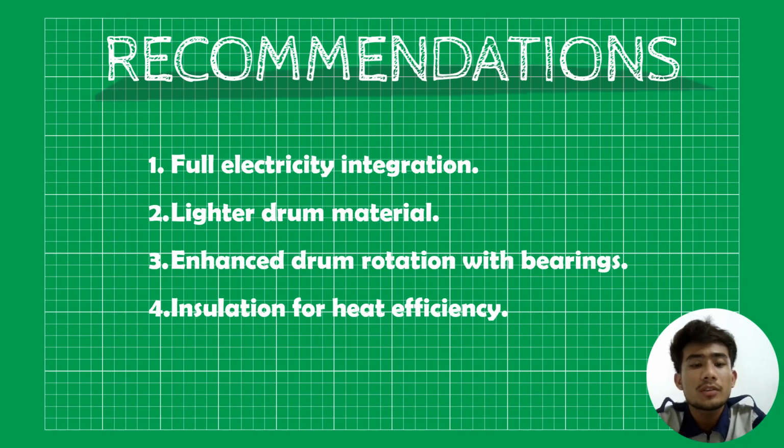The next one is to enhance the drum rotation with bearings. This is to incorporate high quality bearings on the drum shaft to facilitate smoother rotation. This improves the overall efficiency of the roasting process, reduces wear on components, and contributes to a more consistent roast. Ensure that the bearings are heat resistant to withstand the roasting temperatures.